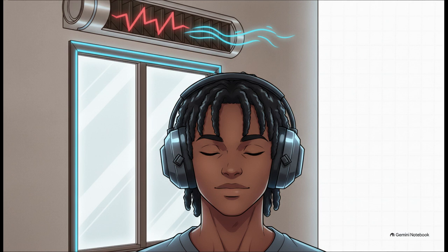For individuals in high-exposure areas, the most immediate step is personal protective equipment, earplugs, muffs, noise helmets, to heavily reduce occupational exposure. But defending the receiver goes beyond gear. It extends to the architecture around them. We're talking about rigorously sealing doors and windows against the outside and installing specific acoustic attenuators on all ventilation openings so that air can flow in, but sound absolutely cannot. Ultimately, it involves utilizing innovative building designs purposely structured to dramatically reduce the intrusion of external noise.